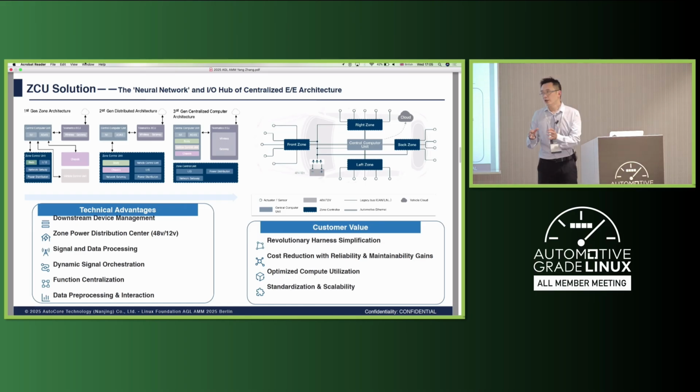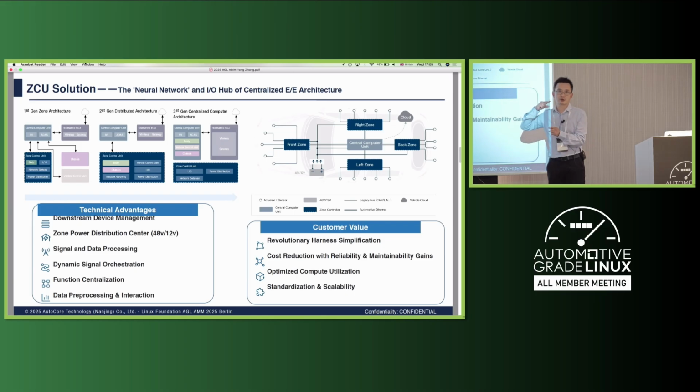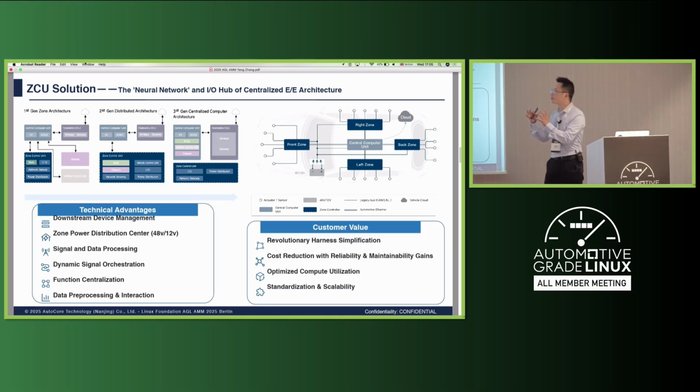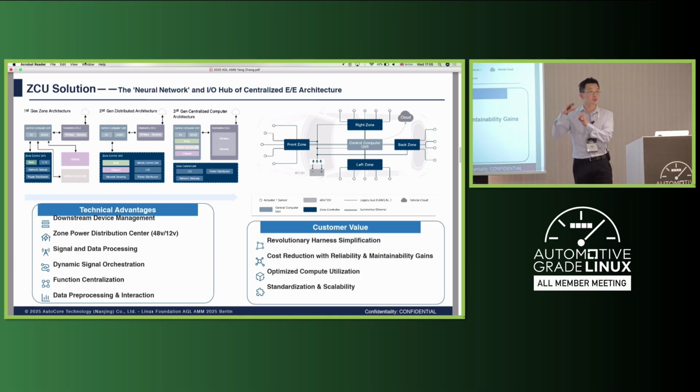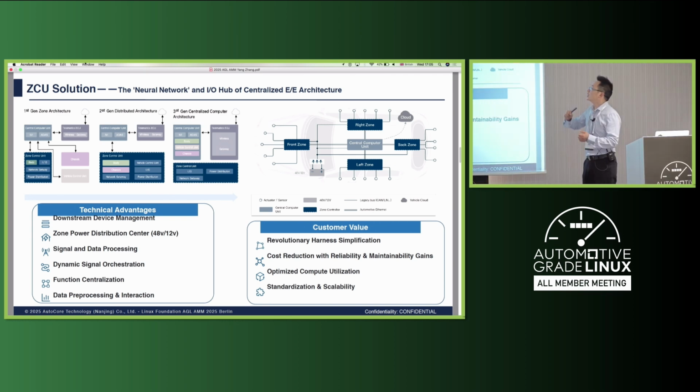For example, if you have a task which is to be executed in the VCU, which is ASIL C or ASIL D grade operations, we will probably treat them as a first priority, because they have to be functional safe regardless. But if you are dealing with tasks which are QM or ASIL A tasks, those tasks and services will probably be coming later as a priority.